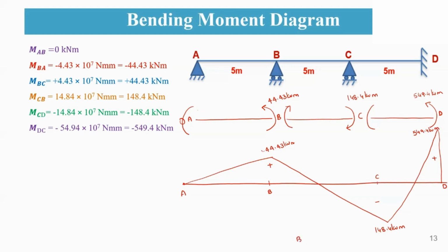So this is your result. This is your bending moment. Here, as there is no external load, we are not combining the final fixed end moments and the simple bending moment. Here there is only the final end moment, so there is no external loading and we are not having any moment due to it. So this is the final bending moment diagram.